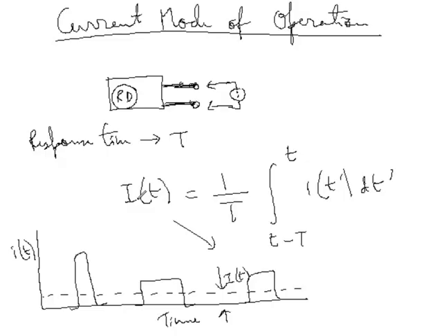The integration time T is quite analogous to the measurement time. Thus the choice of large T will minimize statistical fluctuations in the signal, but it will also blur the response to rapid changes in the rate or nature of the radiation interactions.